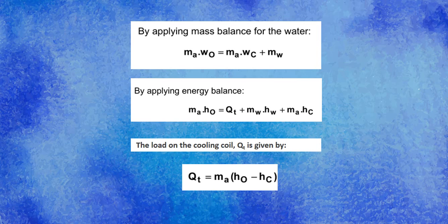So it's mass of water times the enthalpy of the saturated water at the dry bulb temperature indicated at the end of the process, plus this one, the mass of air times its enthalpy at the exit condition that is stated, whether it's in the form of dry bulb temperature or also of humidity, a certain percentage of humidity.